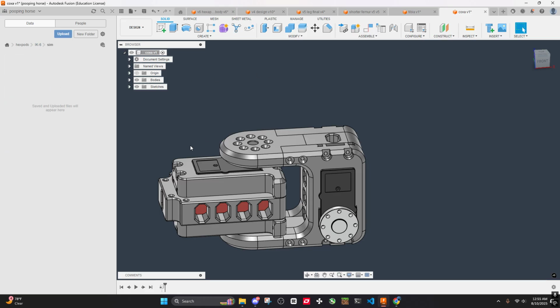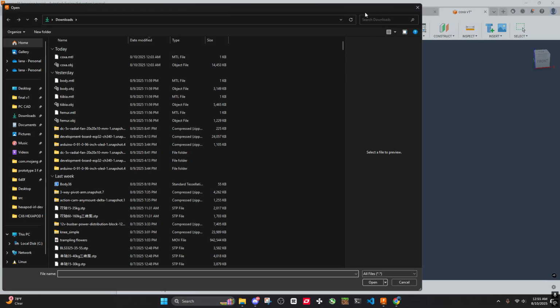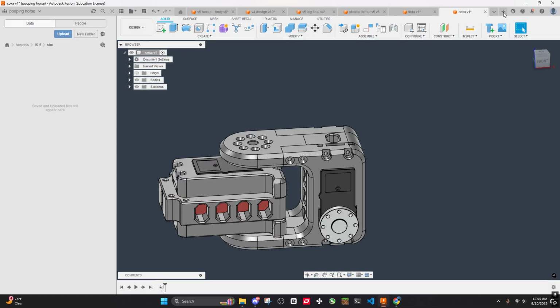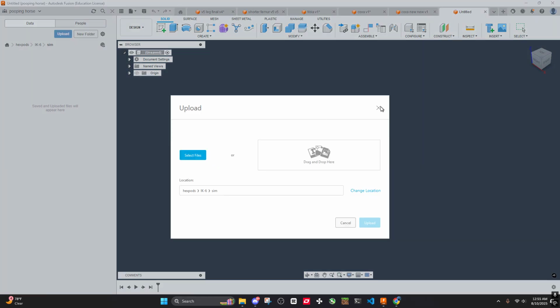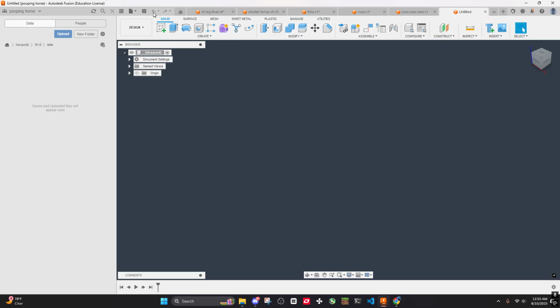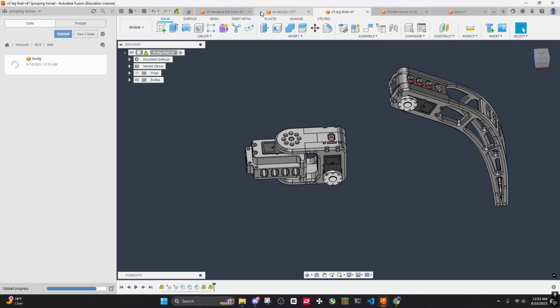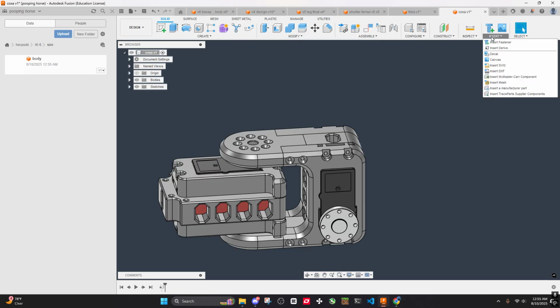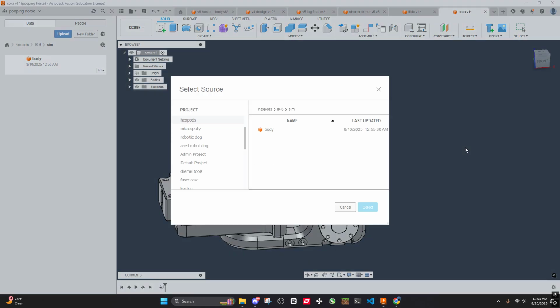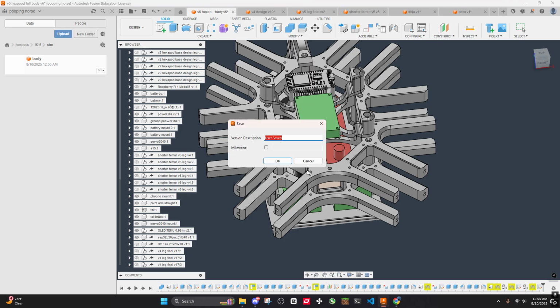Yes, select your object, press Shift S. Oh, maybe I have to do it in layout. Shift S. Cursor to grid, cursor to world, cursor to selected. Cursor to world origin. Yes. Then object mode. I'm in object mode. Yes. Then right click on your object. Set origin. And then which one? Origin to 3D cursor. Oh, nice.